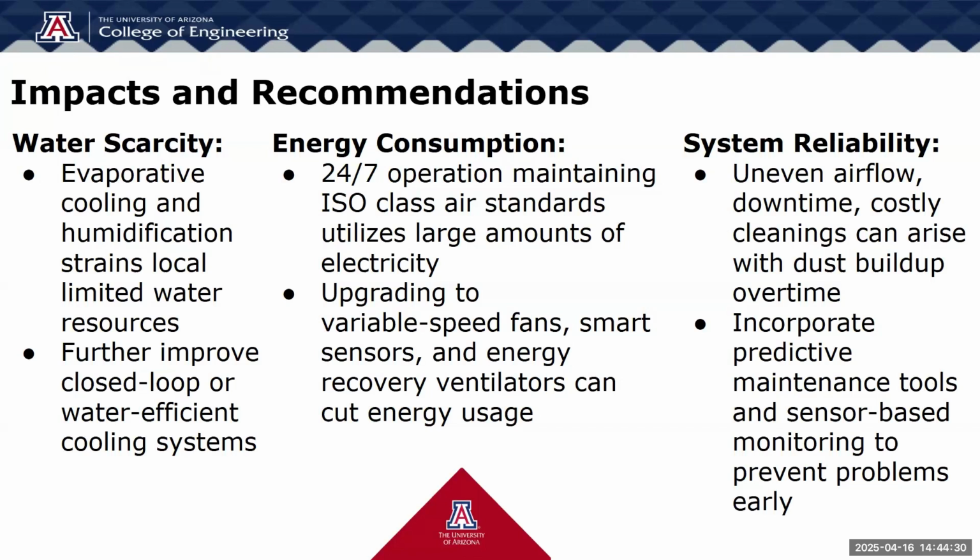Water usage is another concern, especially in Phoenix, where water scarcity is a serious issue. Cleanroom HVAC systems that rely on evaporative cooling or humidification can put added strain on local supplies. By shifting towards closed-loop or water-efficient cooling systems, we can reduce both environmental impact and long-term utility costs. Energy consumption also plays a major role. Cleanrooms require constant airflow, which leads to high electricity use. By incorporating variable speed fans, energy recovery systems, and smarter airflow routing, we can significantly lower energy demand and operating expenses.